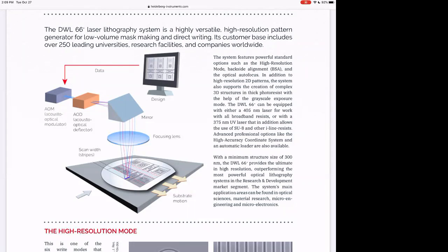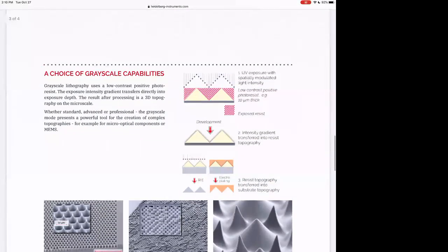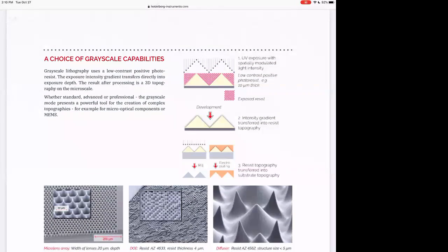But because this is writing on a wafer, this is lithography, which is 2 dimensions, and the third dimension is very thin, versus stereolithography, which is 3 dimensions. So it's exactly the same type of process, but this doesn't build up 3-dimensional structures, except if you modify the intensity and you have differential etching.